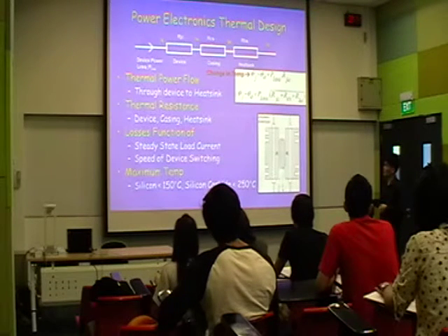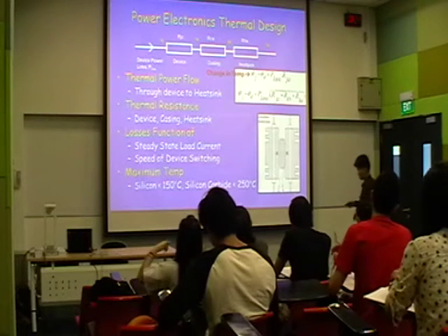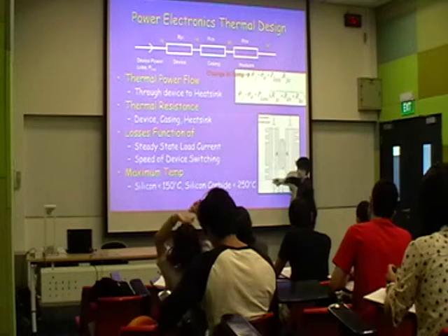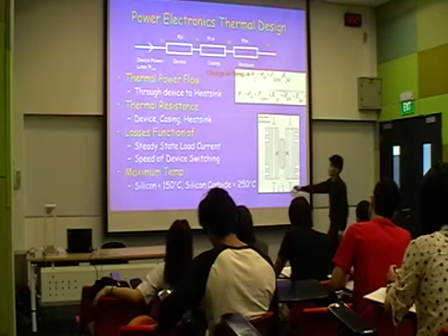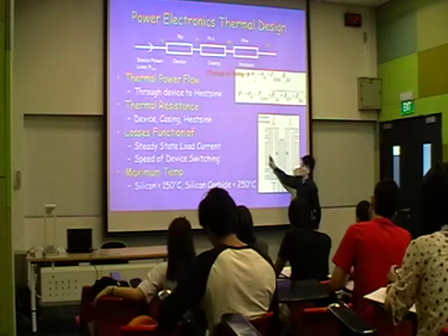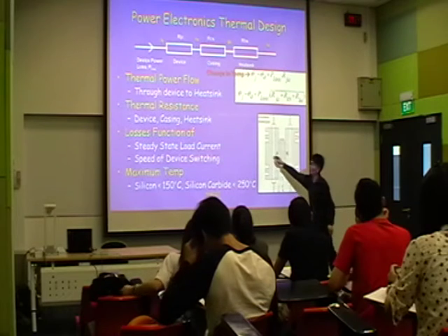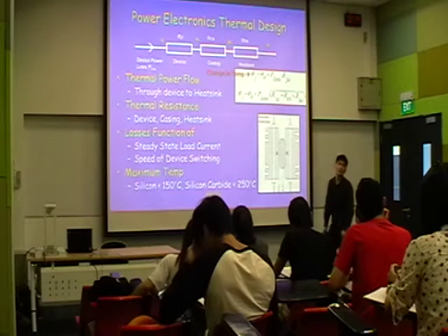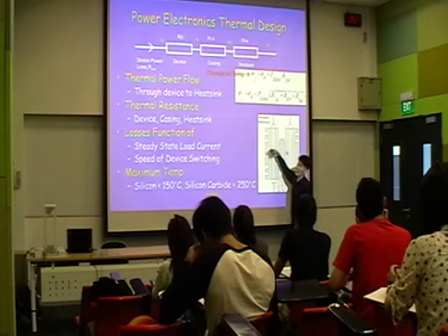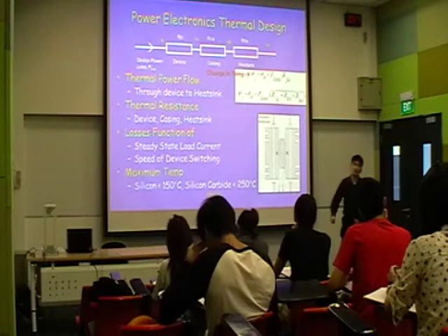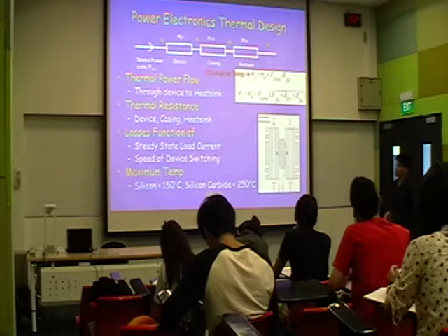You will see that the A part will generate a very high temperature. Because of the water that flows through here, you will find that this part will definitely have a low temperature. As the heat travels from the high to the low, the heat will dissipate. And you can see that this fin portion will help to reduce the temperatures further. So this is how it will be used in some of the shapes.